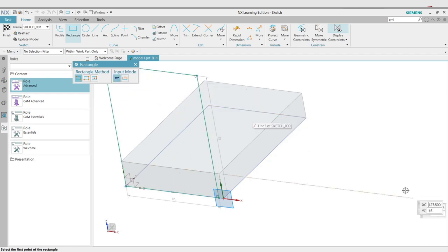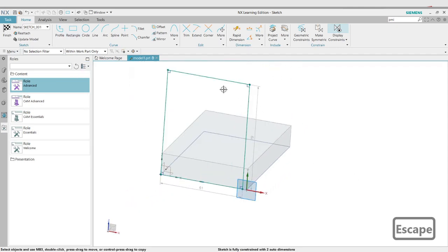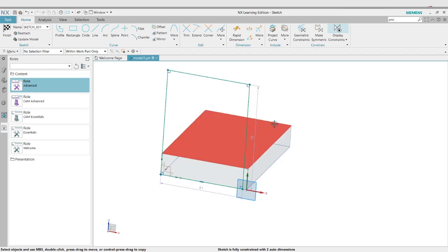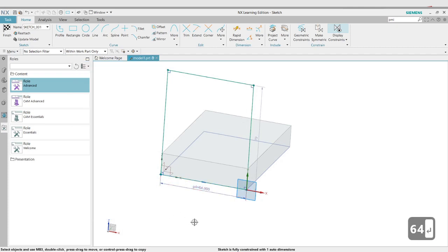So if you notice, we want the width of this flange, it's not really a flange, but this wall, to be exactly the same as this tab we just created. So one way to do it is just to double click on this. These are the automatic dimensions created by NX. So what we can do, we can double click on this guy and specify 64. This is one way, of course, to do it, but this is not really a good practice.